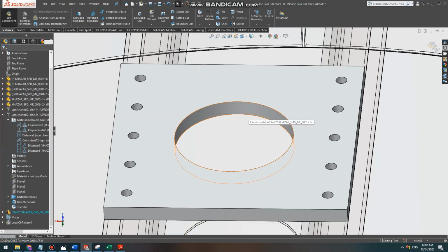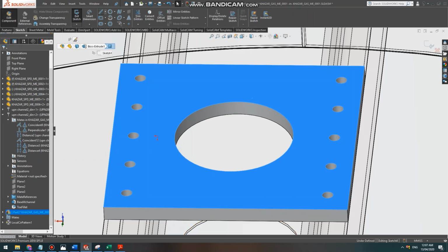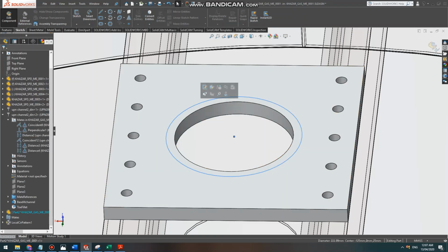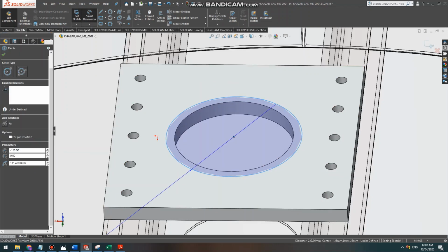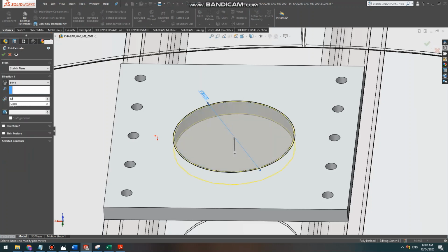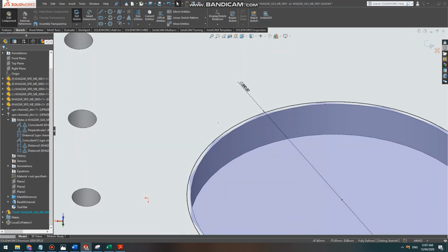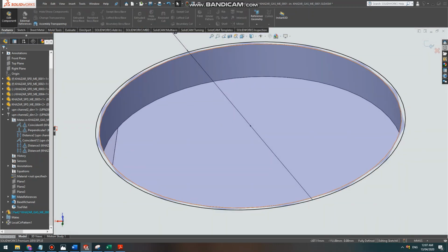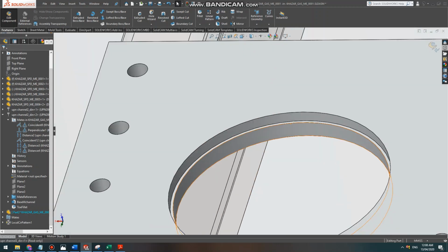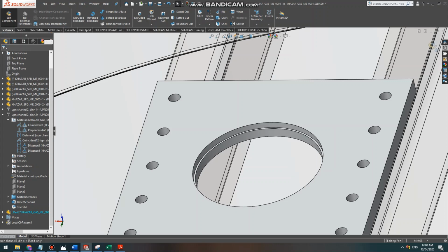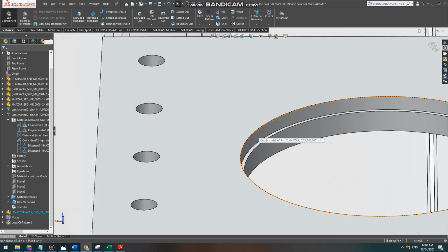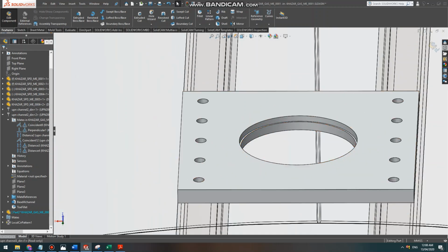This is 195, and also we make another hole which is 200. Wait, so it's 200, and it's extruded just 10 millimeters. So point is, wait, is it extruded? Oh, I want to extrude it. Yeah, that's the point. So the point is when you put the bearing, the shaft on it, it will not move to the right or left or back and forth, because it will be fitted like this, and these walls will keep it from moving.